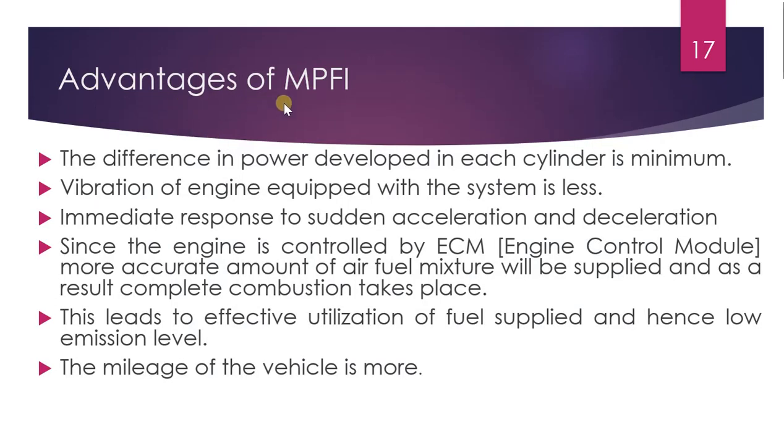The advantages of a multi-point fuel injection system. The first advantage is that the difference in power developed in each cylinder is minimum. If there are many cylinders in an engine, the difference in power developed between each cylinder is minimum in a multi-point fuel injection system because of this controlled fuel injection. The vibration of the system is less, and there is immediate response to sudden acceleration and deceleration because of the sensors associated with this MPFI system.